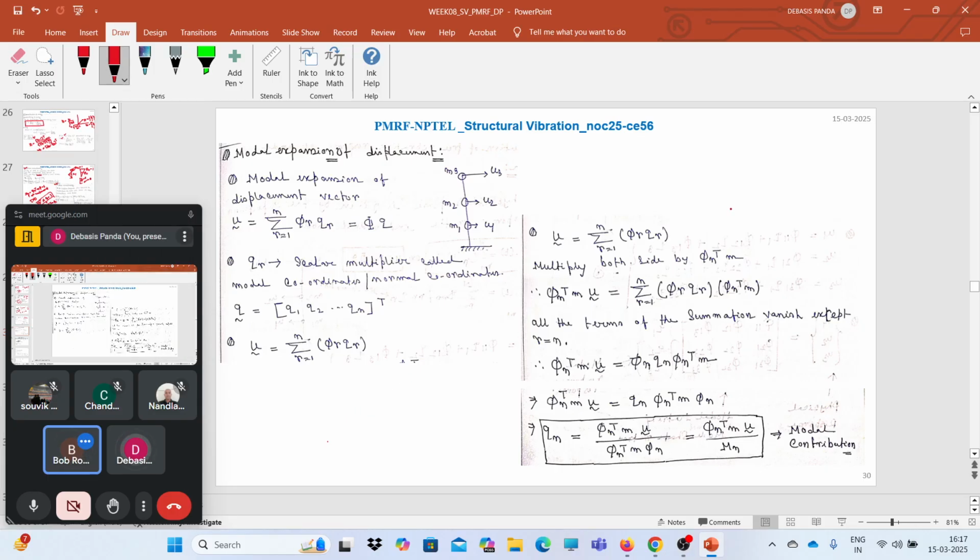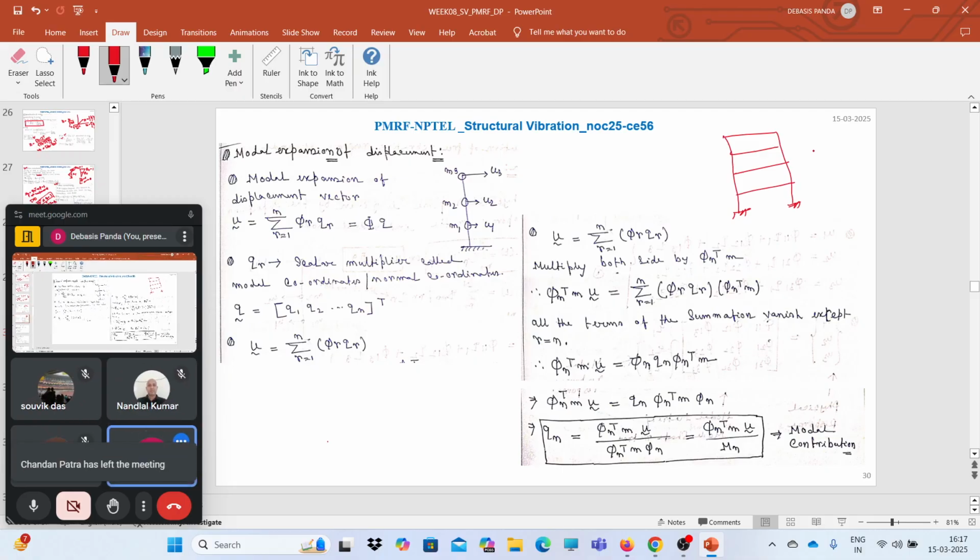Yes. So the first thing, when I solve any kind of multi-degree of freedom system, I look for whether I can write it down in modal coordinates. Because in a multi-degree of freedom system, say for example you have a 3-story building, or a 5-story building, or a 7-story building, that means you have an n-DOF system. For this n-DOF system, obviously you will have n frequencies.